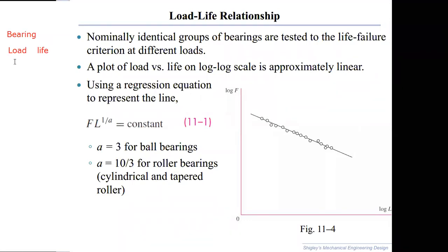What if I decrease the load? What will happen to the life? Life will increase. So this means that whatever load a bearing is subjected to would define the life of the bearing. Nominally identical groups of bearings are tested to life failure criteria at different loads.